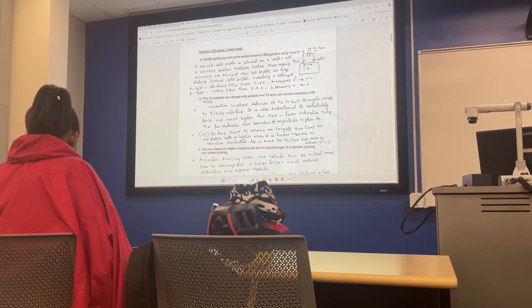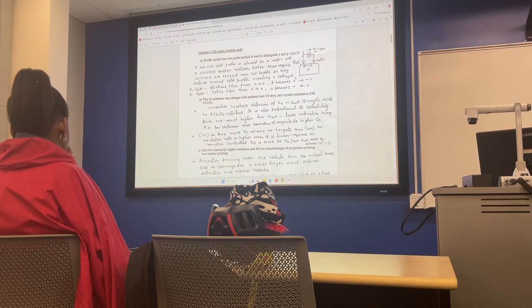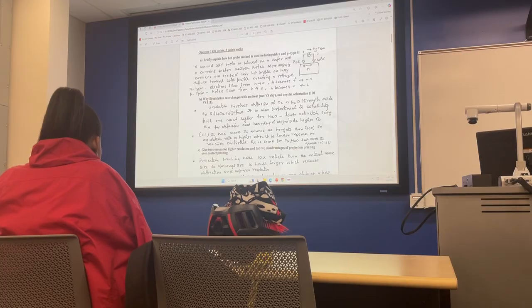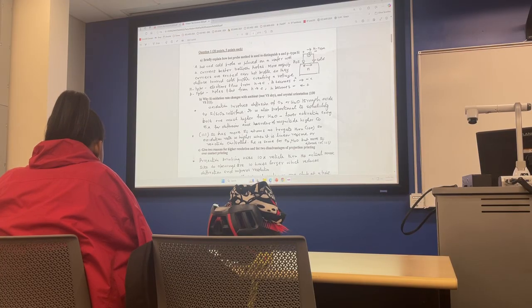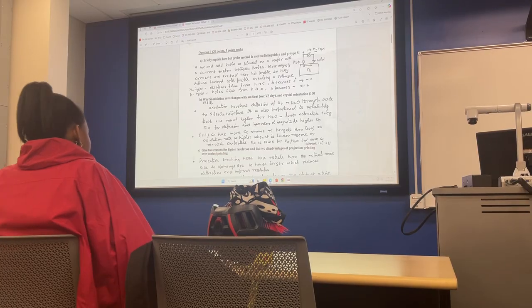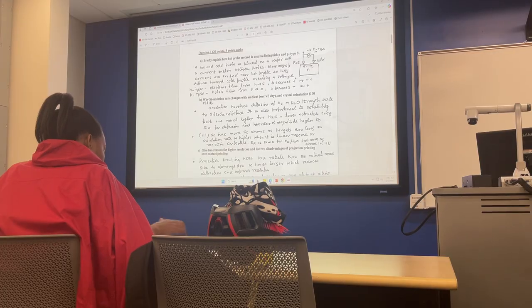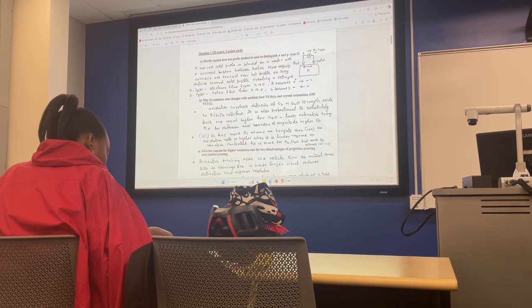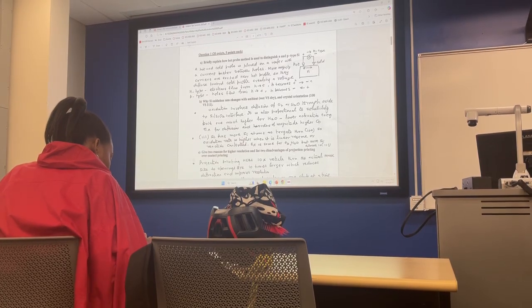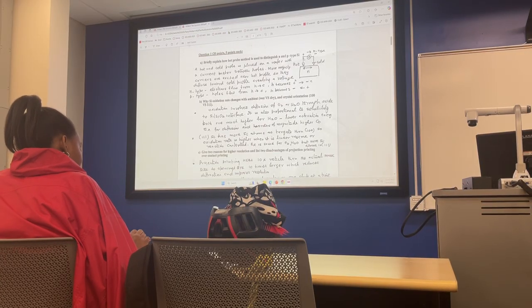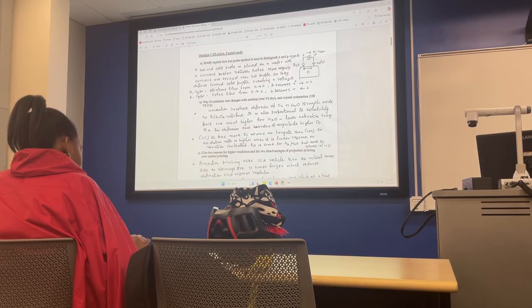And as a result, if you have an N-type, this side you're losing electrons, so this becomes plus, and this becomes minus, right? So the current flows in this side. And the same thing happens if this was a P-type. When holes are majority carriers, they will leave the hot probe and go towards the cold. So that was the answer: in N-type, the electrons flow from hot to cold, right? And therefore this region becomes plus. The current goes that way, and in the hole case it is opposite.